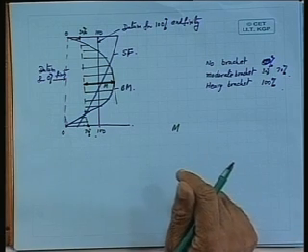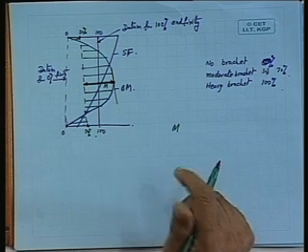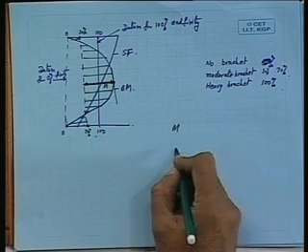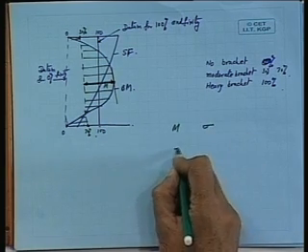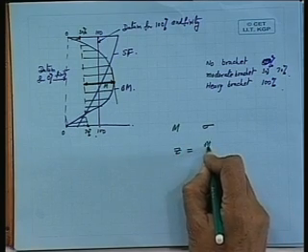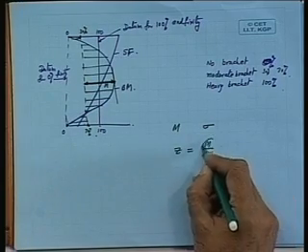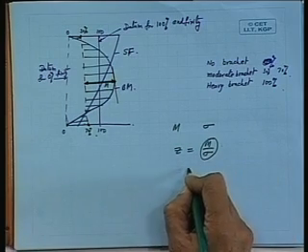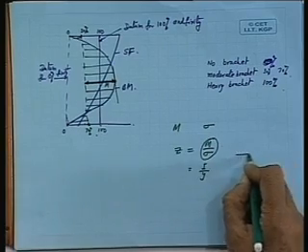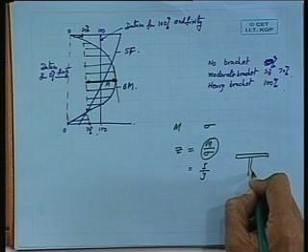and then whatever is the permissible stress value given to me, based on that, because sigma is equal to M by Z. So, I try to find out, because sigma is known to me, the section modulus required, okay, and this is nothing but I by y. And based on this, now I can design what this combination should have.